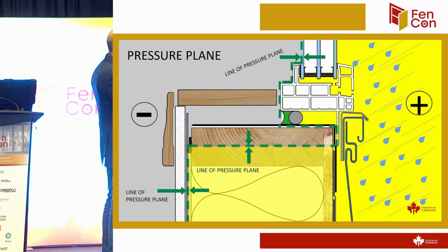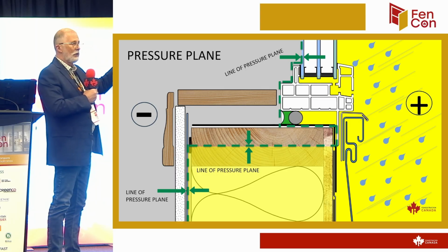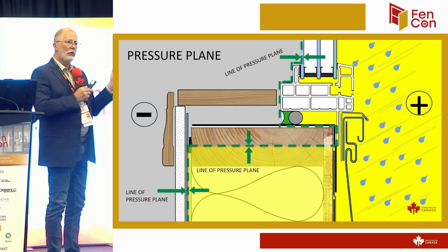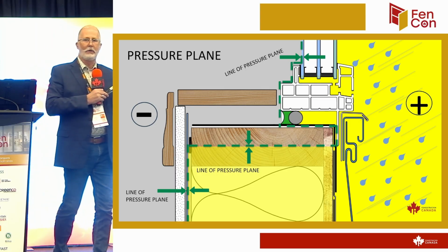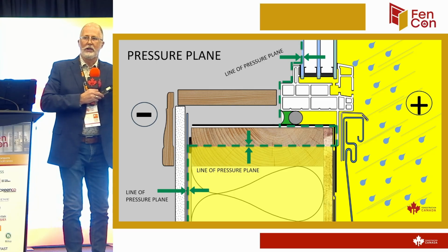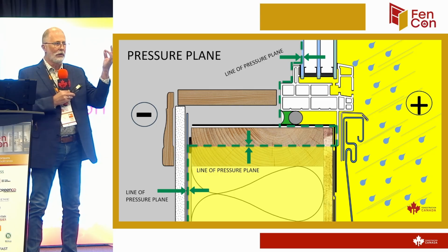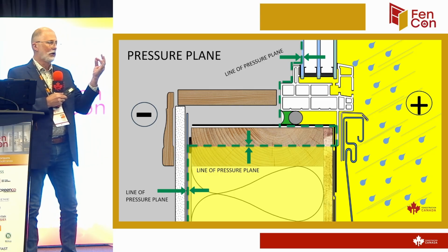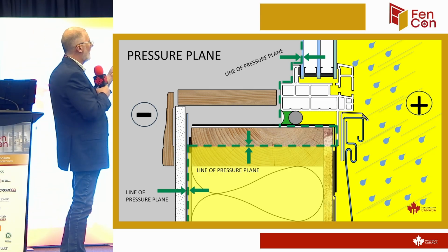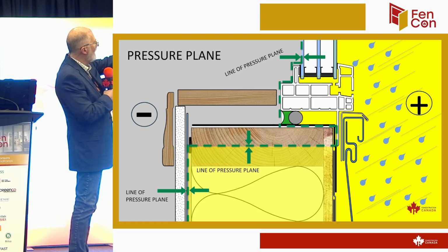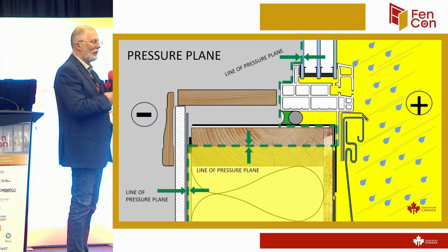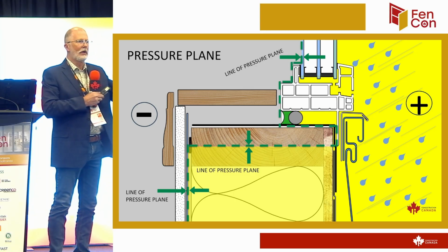And then we carry it back in and we carry it to the inner air barrier, the poly that we put on the inside. Now, where would the weak connection be in that application? Well, if we didn't seal it or put a compression on that, it could create some ability for air to go through. But if we maintain that nice airtight seal, the water that gets in there has no reason to stay, it just drains back out again.